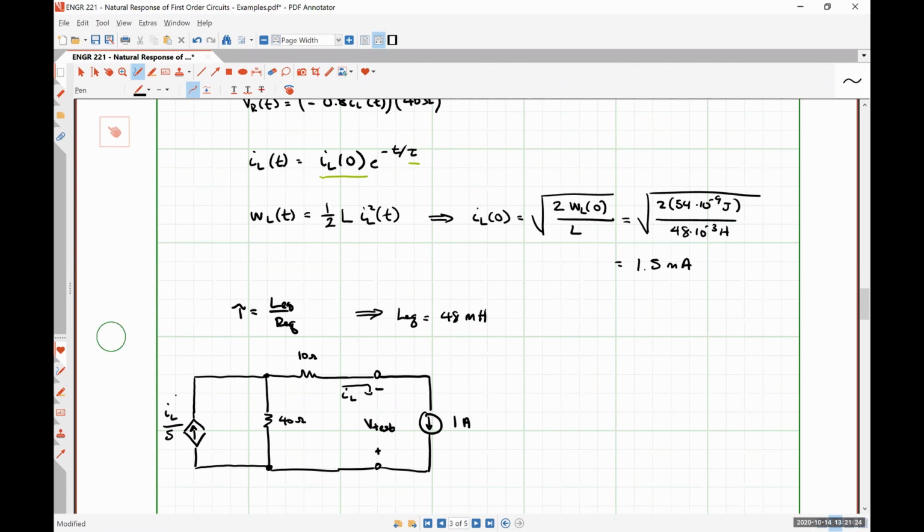So we know that this guy is now essentially a 0.1 amp source, right? So it should be pretty easy for us to figure out what that voltage V-test is. So I'm going to use nodal analysis. I'm going to put my ground here. I'm going to call this node VA and this node VB. Those are the only two nodes I have in my circuit. And it should be obvious then that VA is exactly equal to V-test in this configuration. Everybody okay with that?